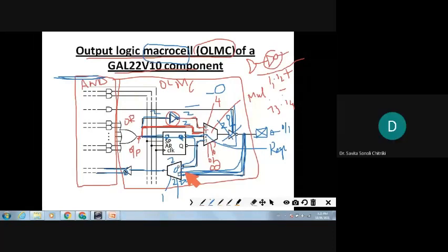Okay, it contains register. In a broad manner, what is the difference between PAL and GAL? In PAL, you are getting only one output, and that too is an inverted output, through an OR gate. Do you agree with this? Whereas in GAL, you have various different outputs.